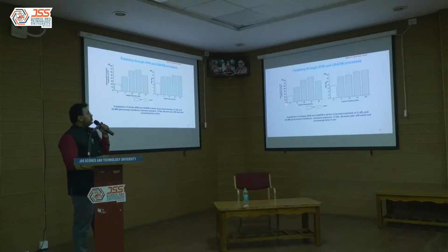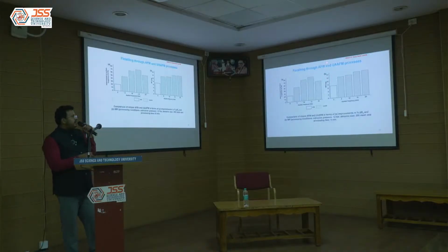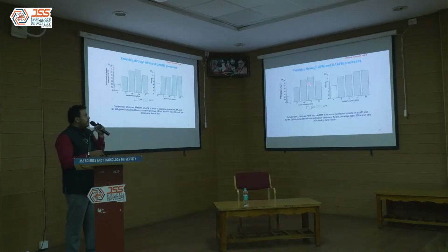So this graph shows the finishing through AFM and UAFM. AFM means abrasive flow machining. UAFM is ultrasonic assisted abrasive flow machining. We can observe the clear trend that whenever you are increasing the frequency, there is an increase in the surface finish, and after some extent actually it is slowly deteriorating. That is maybe because of more abrasives interacting and forming some scratching because of high applied frequency.